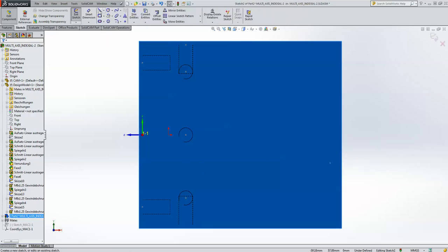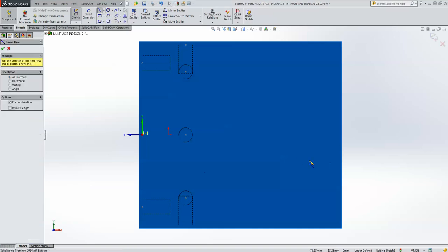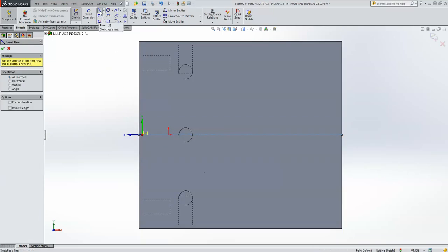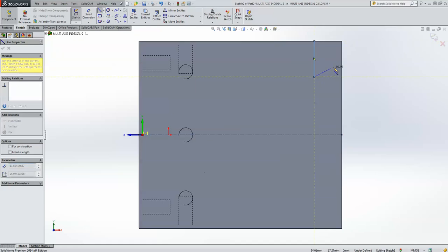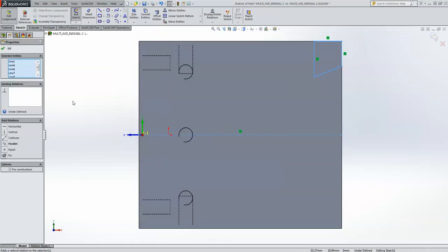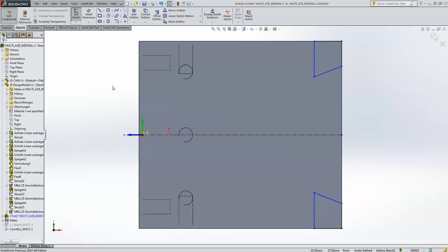And just as I did before, I'm going to choose the center line first. Start from over here all the way up to that point over there. Then choose the option of creating a line and do exactly what I did last time also. But this time I'm creating, like I said, a completely new part. Go over here, up to that point over there, and now grab everything that I have over here, including the center line, and just click on Mirror Entities.